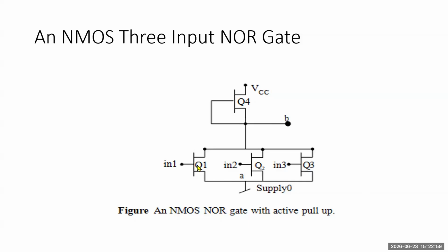And for lower transistors, we are going to use 3 NMOS transistors. We have to instantiate the ideal MOS switch NMOS. Within the parenthesis, we can represent the inputs and outputs. Here supply 0, a net A is connected to supply 0. Output is B here. And supply 1 is not represented. We are not using supply 1 directly, since we are going to use it as pull-up of B. No need of using any supply 1 also. That statement supply 1 here.